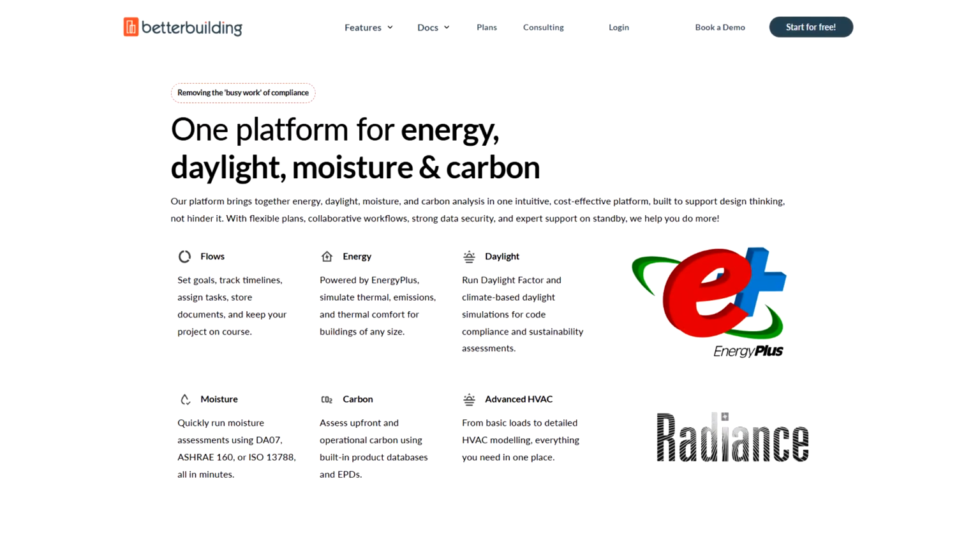What do I mean by that? Well, pretty much you can jump in there, use EnergyPlus on the back of our platform in order to undertake energy related calculations, and that could be thermal, could be emissions, it could be comfort. You can design advanced HVAC systems, and EnergyPlus has been an incredible resource for us to both learn and apply on the platform. We've also got Radiance there, and that helps us obviously undertake daylight sims.